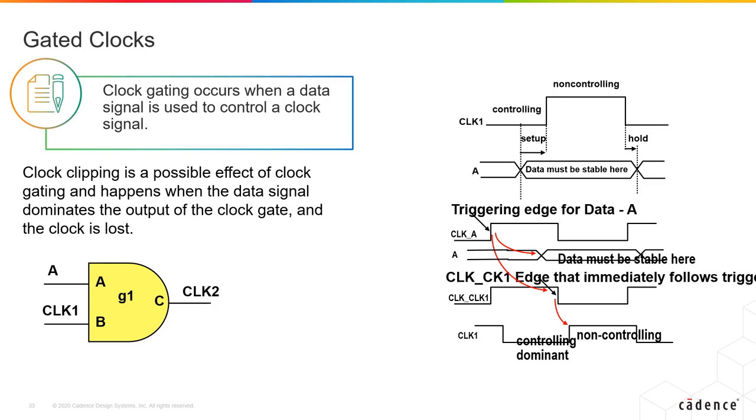So any ports that are related to CLK1 will all get the same slew and uncertainty in the case where your input A is at logic 1. Just like all other signals, the output also has rise and fall times. The fan-out of the clock is much greater than those of most other signals. The output slew degrades as the now-gated clock signal propagates, controlled by the enable signal A.